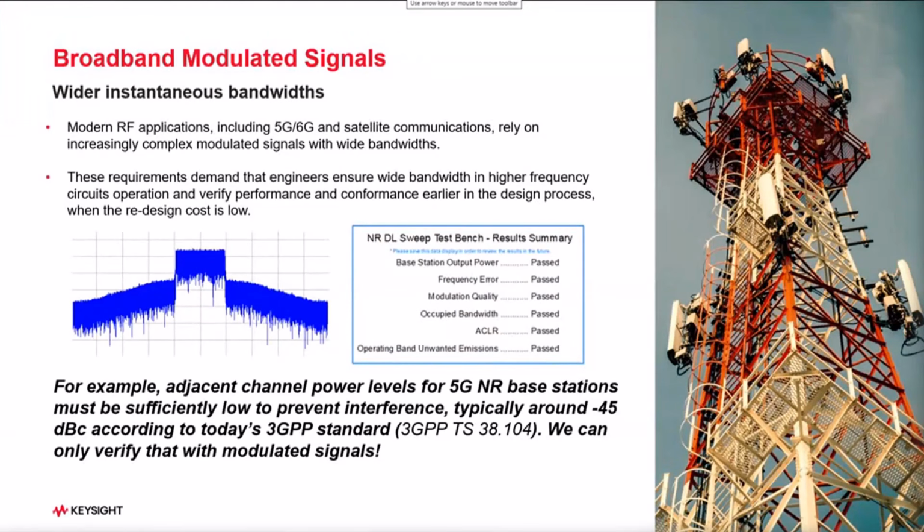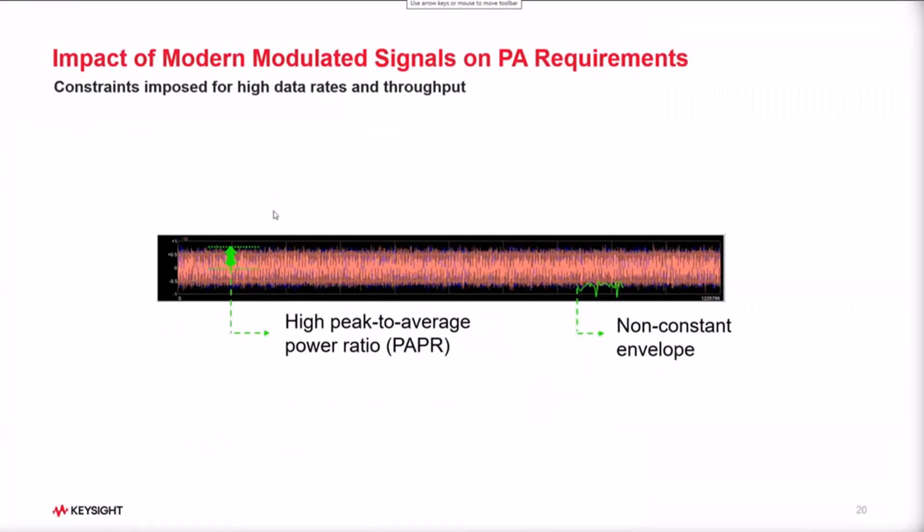Now if you take a Wi-Fi 7 example, you have a 4096 QAM signal. Imagine the modulation density and what kind of symbol to symbol spacing you have. These complex, denser modulations are giving you less and less freedom. You have to be very precise, right? That means one tone, two tone is not sufficient.